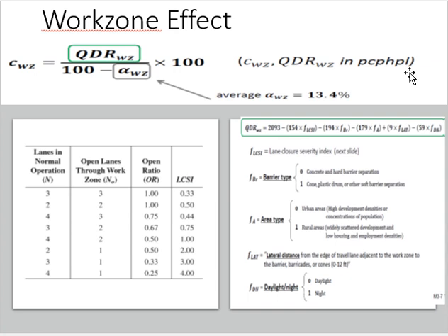I should know how many lanes normally are on the highway and how many are still open with the work zone. Now you're doing some construction activity, so you may close some of the lanes. It can happen, right? So what is the normal and what is with the work zone? If you know these two, you can know FLCSI.